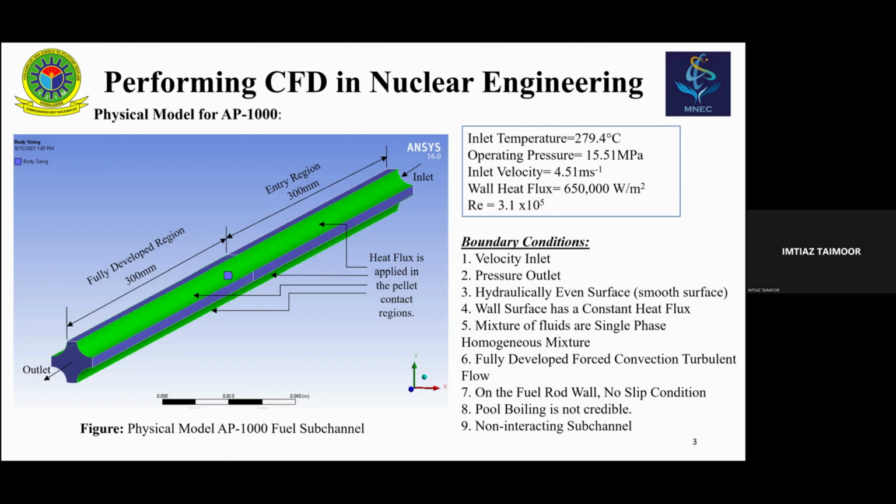Control volume, I think you have learned this term in your fluid mechanics course. This is the control volume. It means the specific part of the volume of a system in which we are interested, and we are considering that the mass within the system remains constant, the momentum within the system remains constant, and the energy within the system remains constant, regardless of the operation that you perform within the system. So that means we have to apply three equations: the conservation of mass, the conservation of momentum, and the conservation of energy.